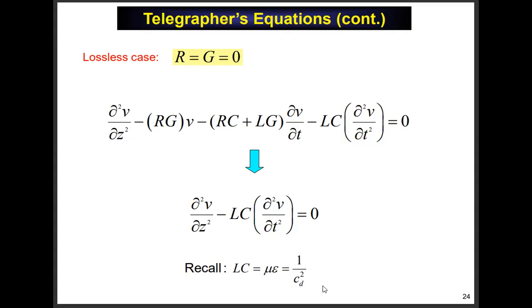Now, you might have a transmission line like the twin lead, which for all practical purposes has the conductors in air, so C_D would be equal to C. But for most transmission lines like coaxes, they're filled with insulating material like Teflon, so C_D is less, of course, right?